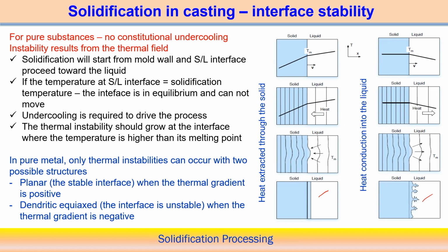But in the case of the alloy system, the instability involves both the temperature conditions as well as the concentration gradient of the alloy system, or I can say the constitutional supercooling, because constitutional supercooling is a change of composition in the solid liquid mixture during the solidification process of an alloy. So that actually brings a different instability condition associated with the solidification of an alloy system.